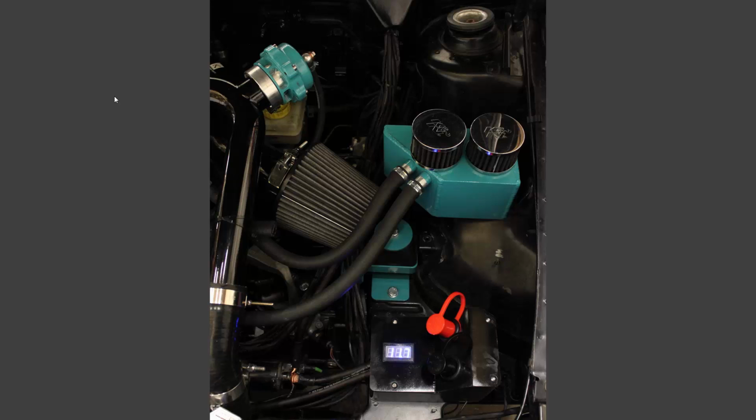So you can see I skipped a few parts as far as post-processing the printed parts. I did kind of a 2-step post-process. You see down in the bottom corner there. The printed parts have been sanded. I sanded them with 150 grit sandpaper, and then I painted them just using regular Rust-Oleum spray paint. I used a sandable primer, and then just a gloss black enamel.